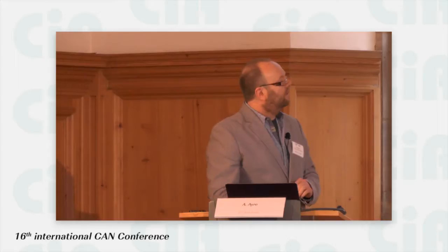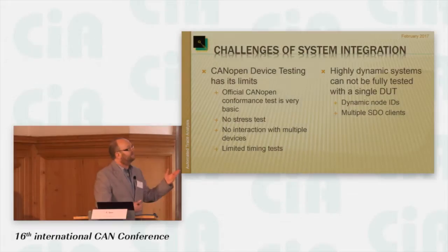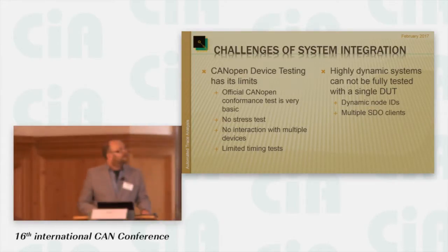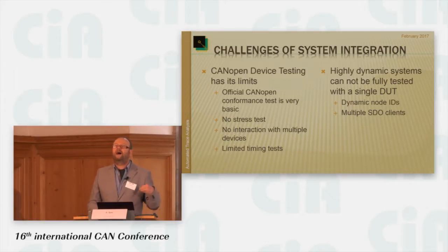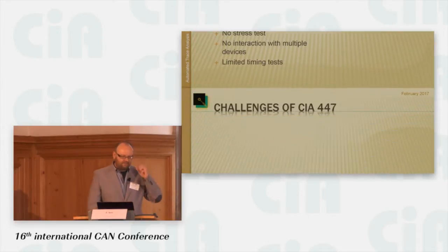And you can really see that specifically in highly dynamic systems, this gets pretty complex with regular testing methods, because as we said yesterday, if after every boot up the layer setting services are used to assign a new node ID, with every system start it could happen that devices have a different node ID, then it becomes particularly difficult to double check who is at fault, who did what in a system.